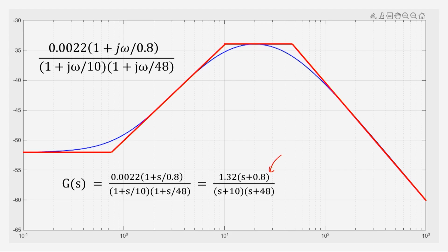You can give different inputs to this transfer function in the simulation world and see what the output would be, and then carry out the same experiment on the actual hardware you have, and then match the magnitudes and the phase. If they are matching within some tolerance, then you have the transfer function. If not, then you tweak the position of the poles and the zeros a bit to fit that transfer function. This is how we can manually do this.